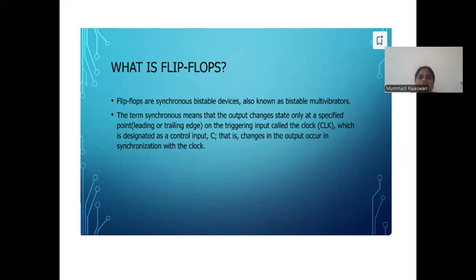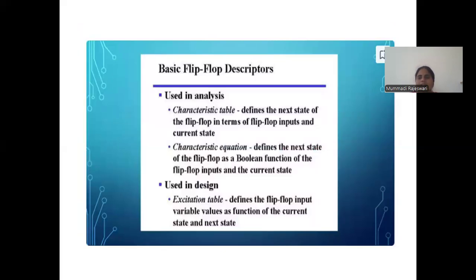The term synchronous means that the output changes state only at a specified point, that is, the leading or trailing edge of the clock. Means the output changes only depending on the clock signal. In flip-flops, the clock depends on the leading or trailing edge of the clock. In latches, the output depends on the positive level or negative level of the clock, the level sensitive clock. The output changes occur only in the clock.